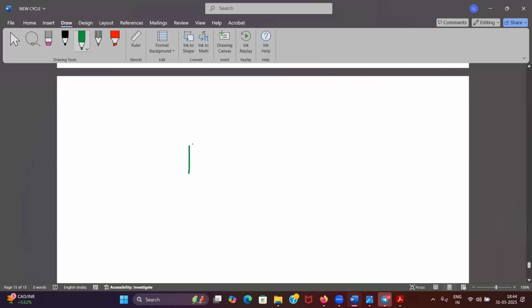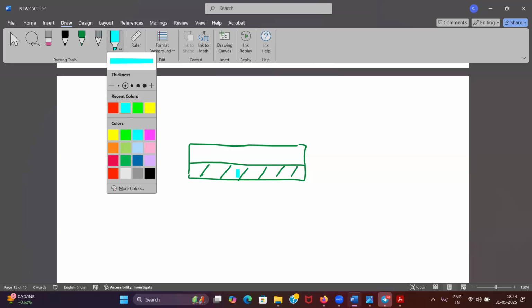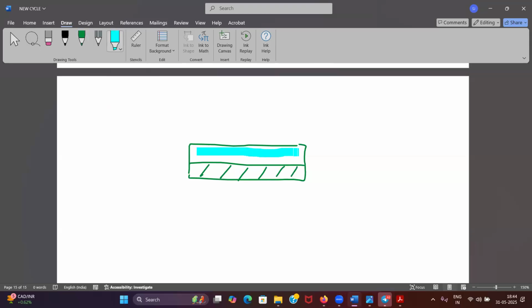So this is your condenser. This is your liquid refrigerant, and you have certain air here which is not condensed, that you want to vent out. Straight away I cannot just open the vent and release it in the atmosphere. It might have certain vapors of refrigerant also.